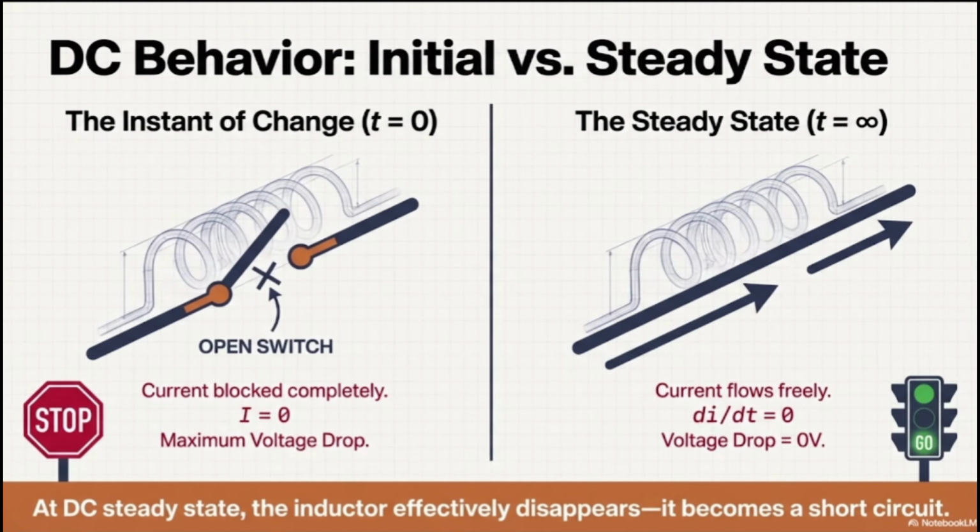Another important thing that we have to know is the behavior of your inductor itself. As I just told you, the inductor, like the capacitor, doesn't like change. In the capacitor, the change was about the voltage, but at this point, the change is about the current itself. So as you guys remember, we had the formula V equals negative L di/dt, but we don't consider the negative sign itself. I'm going to say L di over dt. Again, d means the small changes of that variable, which at this point is I and t. So V equals L di/dt, and this guy cannot change that fast.